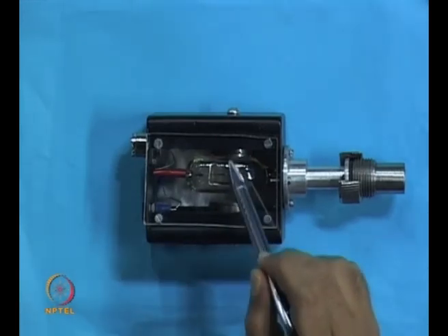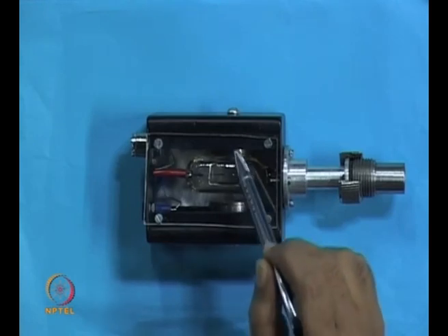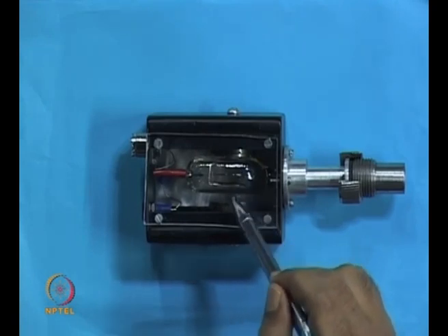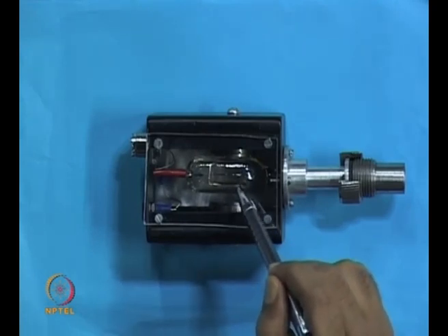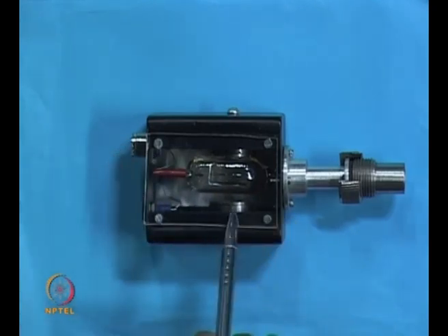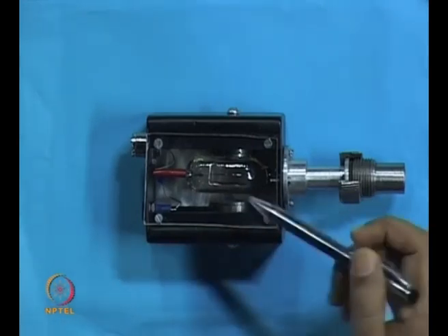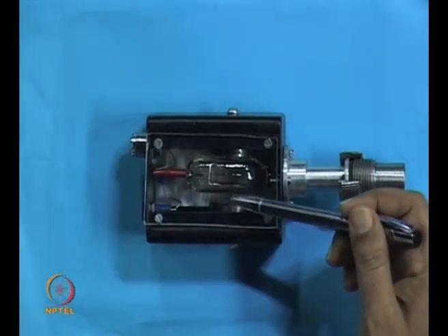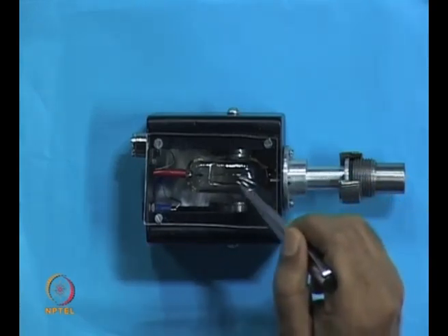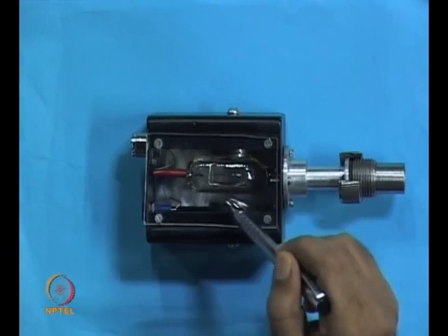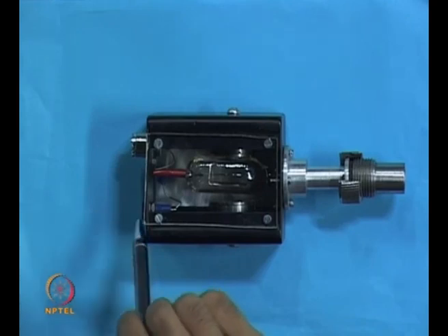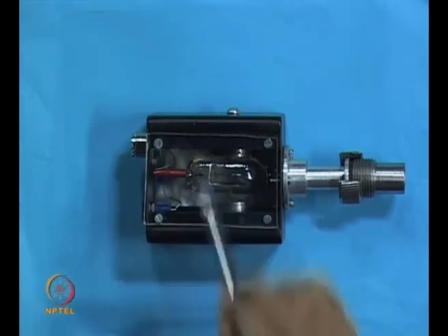Also, what you see on either side is the magnet. You have a permanent magnet over here. So you can see the magnet, you can see the cathode, the cold cathode, and what you see in the middle is the anode, and a high voltage is supplied to the cathode from this side. Whenever the electrons get released from the cathode to the anode, the residual gas will come in between and get ionized, and this ionization current is going to be fed to the gauge over here, which is calibrated as a function of this residual gas pressure.